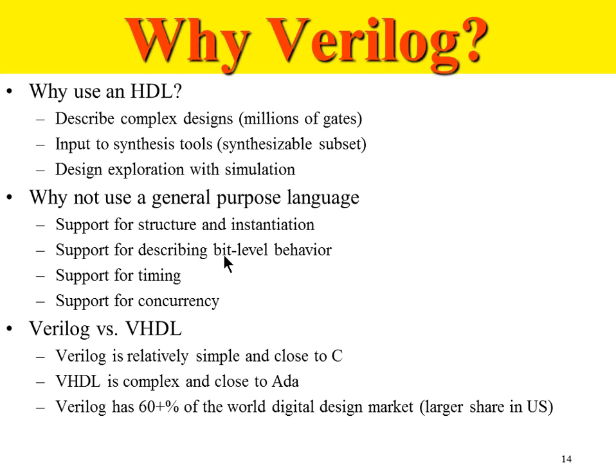Very simple design. I can individually control the operation of 8 different LEDs which are connected to individual bits of the 8-bit bus. So using the current version of embedded C language, I can control those.